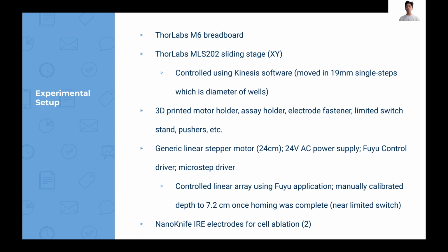We're also using a graphical user interface application for the linear stepper motor, which we use for controlling the depth of the electrodes in the cell wells. We calibrated that to about 7.2 centimeters from the limit switch. Finally, we're using two NanoKnife IRE electrodes for the cell ablation, with which we apply the pulse electric fields.